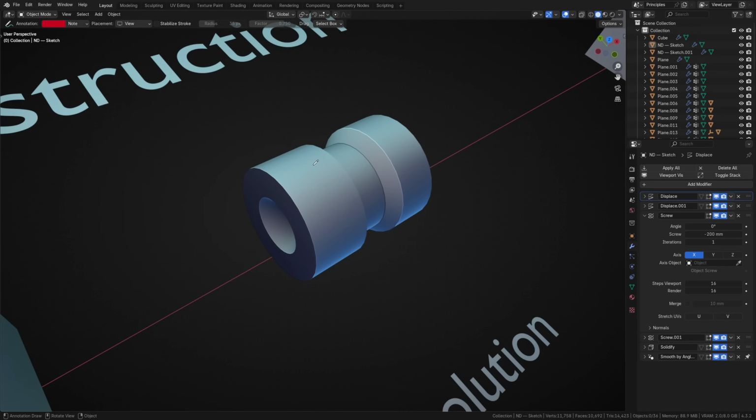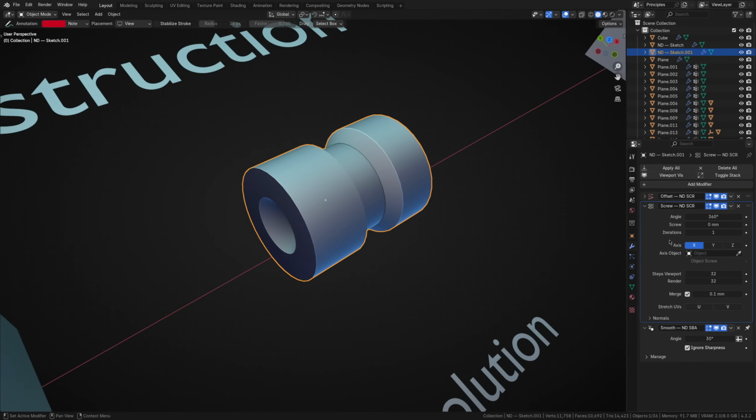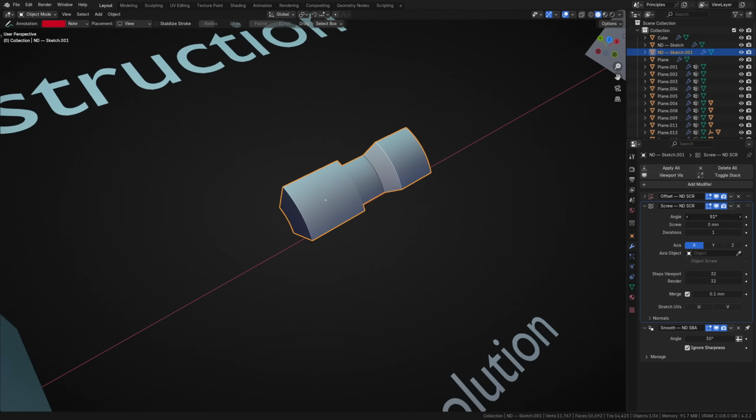Back to revolution. To reverse a revolution operation, start by imagining a seam running down the object's length. If converted into a plane, the seam should cut through the object, mirroring it on either side. You can then imagine the object compressing back on itself in a clockwise or counterclockwise motion around an axis in line with the seam. If we unwind the revolution operation to 0 degrees or remove it entirely, we'll be left with a planar surface.